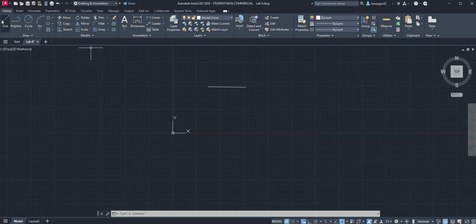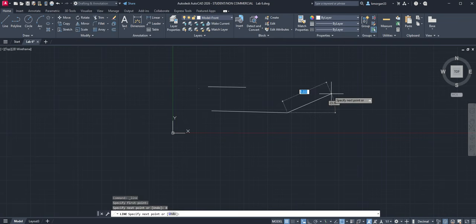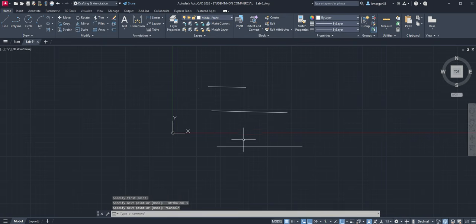So go ahead and practice again and again with different distances. First you click on it, and if I want to go 8 distance, you click on it and it will do it for you automatically. If you want a very straight line, you click on F8, and let's say I want to go distance 9, it will give you a perfect 180-degree line instead of a little bit of an angle like you have here. F8 is your auto mode, which is this line right there. Now I'm going to go back out of F8 by clicking this, and it will turn off.